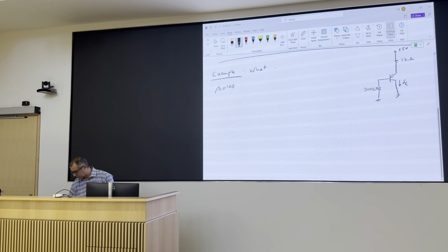Measurement of voltages on a high impedance node is tricky because your typical multimeter has a 1 mega ohm input impedance. If you have 300 kilo ohms of resistance there, 1 mega ohm is comparable to 300 kilo ohm. Your instrument affects your circuit and changes the voltage at that node. Your circuit that was happy before you touched it may become unhappy. Or you think the circuit is saturated, you put your probe there and everything is good.